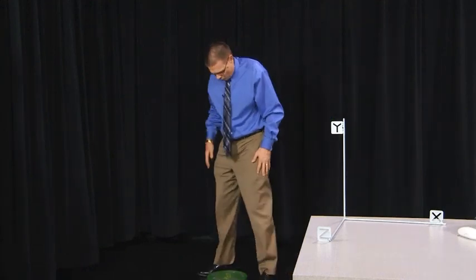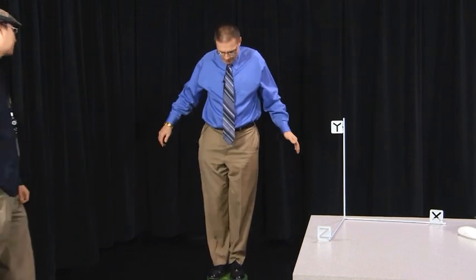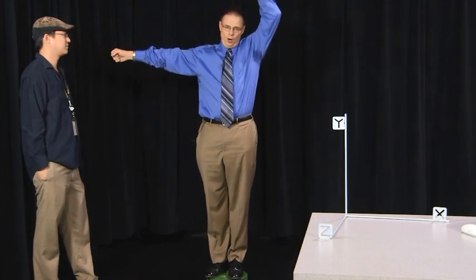And so I want to do a little demonstration here for that. I am the body now. The z-axis is going to go through my head down through the platform. I'm going to start out with a whole lot of mass that's away from the axis. I'm going to keep my arms out. So I've got a lot of mass moment of inertia, a lot of mass located far from my axis of rotation. And so then I'm going to bring my arms in, which is going to reduce my mass moment of inertia because I have less mass away from the axis of rotation, which should allow me to increase my angular acceleration.